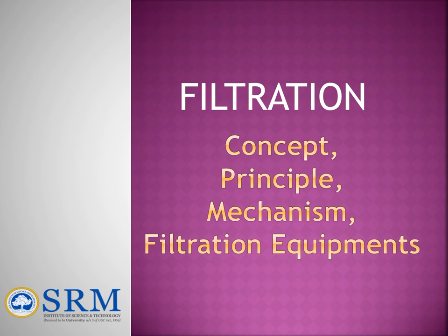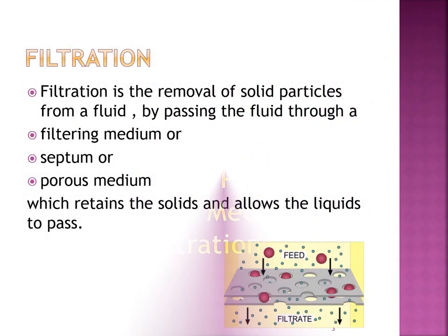Filtration concepts, principle, mechanism, and equipments will be discussed in this video. The definition of filtration is that it is a removal of solid particles from a fluid by passing the fluid through a filtering medium, septum, or through a porous medium, which helps to retain the solids and allow the liquids to pass through. As we see in the picture, the liquid permeates through the filter medium and the solids are trapped within the filter medium. The liquid which passes through the filter medium is known as filtrate, and the solids which are retained on the filter medium is known as cake.